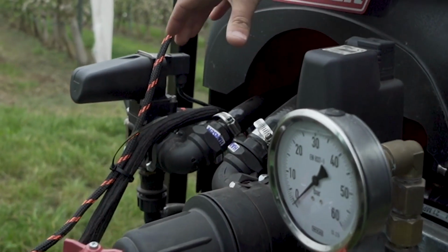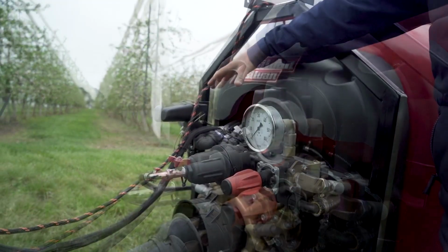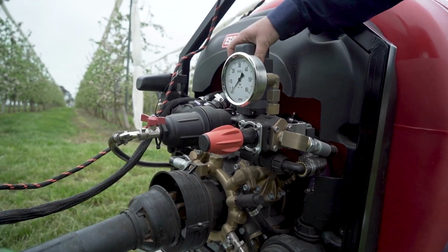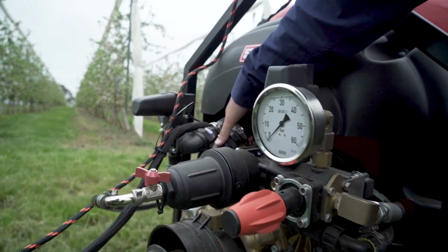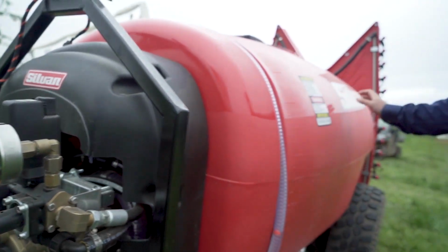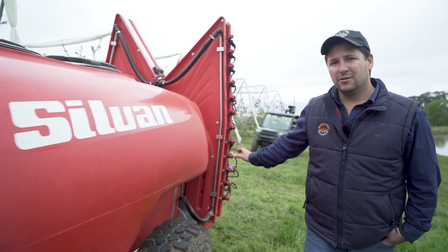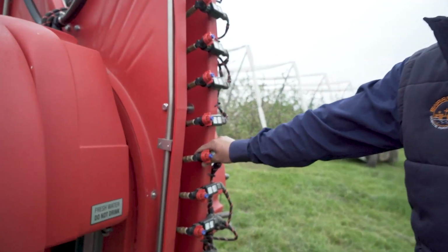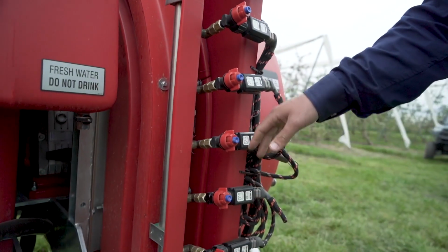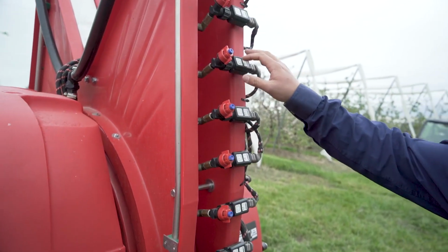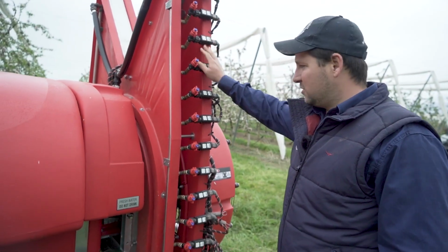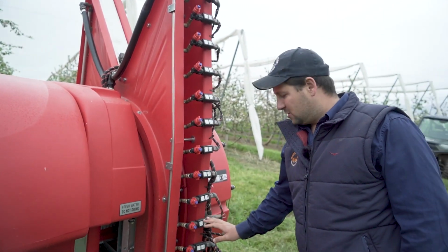It used to consist of 4 section control valves here so that we could target the tops and bottoms, left and right hand side of each tree. We've removed that and now we just have the plumbing comes directly out of the pump and straight to the rear of the machine, where we have individual nozzle control thanks to the Hawkeye nozzle control valves. So instead of having sections for the top and bottom that were controlled, we now just have individual nozzle control. So we can turn on any single nozzle individually. Commonly, we'll group them into tops and bottoms, but we do have the ability to target every single nozzle separately if desired.